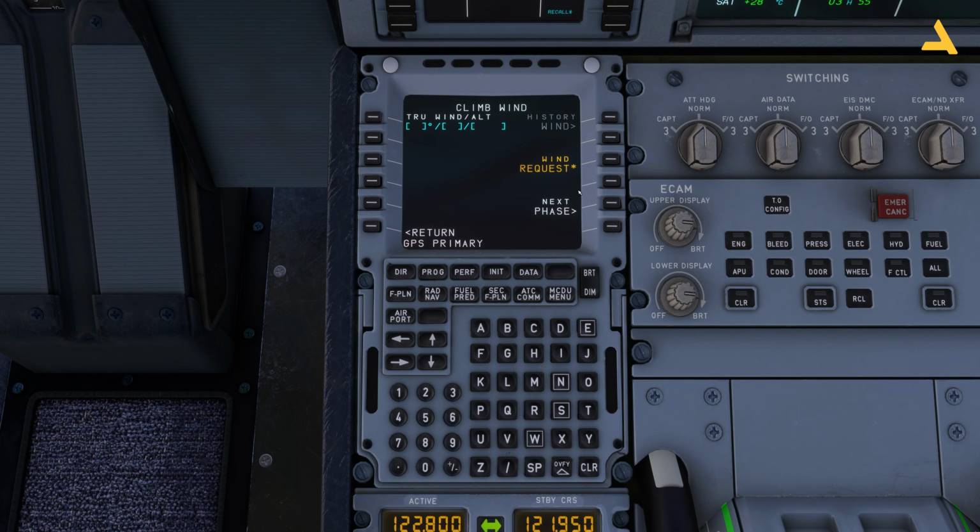And if you want to get the wind information for this trip, you can just request this information, and you can see that at different flight levels, the wind direction and magnitude is given. This is basically flight level 180, which is 18,000 feet. And then you have it for the climb and cruise, and for the descent, and that's it. So let's go back.